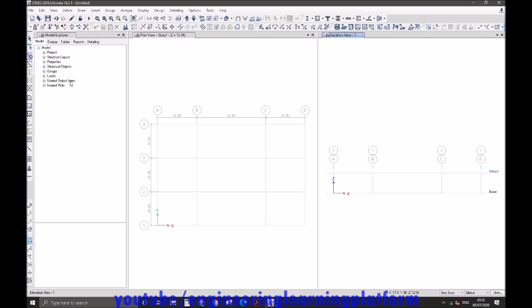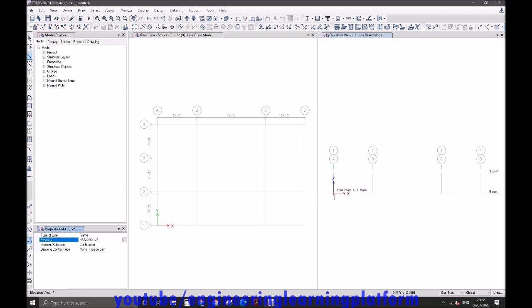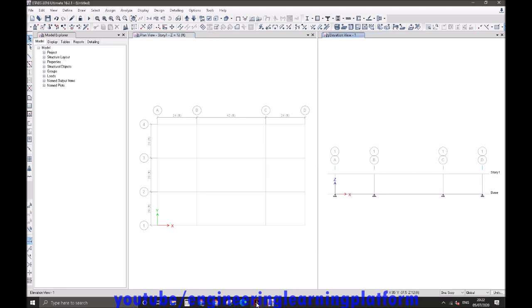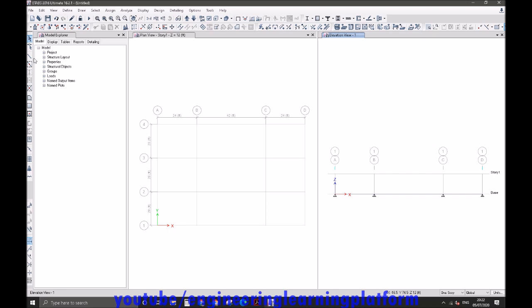Now, starting with the modeling part in ETABS, we'll proceed with modeling in the elevation window. Here we have rectangular sections. At each joint we are modeling them. Now for the rest of the members, we need a snap on the midpoint of the structure.